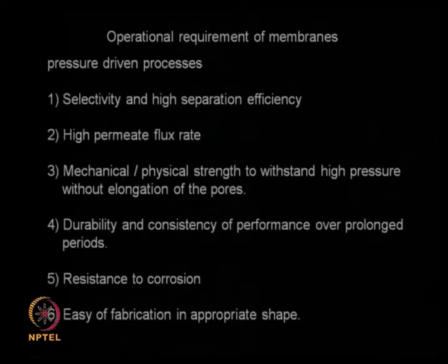There are many operational requirements in a membrane process, so you need to keep all those points in mind. We want to have very good selectivity, we want to have high separation efficiency, so this is the fundamental point. We want to have high permeate flux rate, that means the rate of filtration has to be very good. The membrane should have good mechanical and physical strength to withstand the high pressure. Continuously you are operating at such high pressure, so your mechanical strength should be quite high. The pores should not get elongated because you are continuously applying a mechanical force.